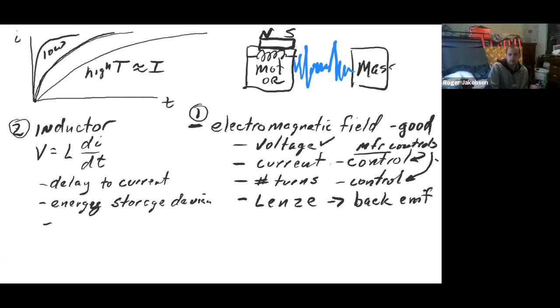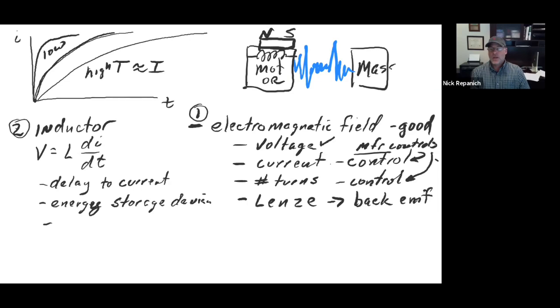Well, wouldn't that really depend on the application of the motor? If you need a fast reacting motor, but it doesn't have to be that powerful, wouldn't you switch to a low inductance motor? Absolutely. It's exactly right. When you go to choose a motor, you decide, okay, it's a NEMA 23, it's 2.3 inches, and it's a single stack.